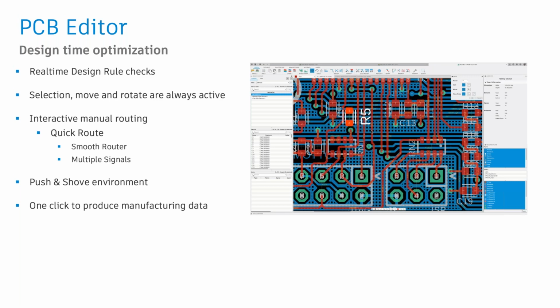Traditionally, users would have to delete any obstacles that are in the way. They would have to rip up, in other words, any work they've done would be a total waste of time. They would have to erase these components, place the new part, and then do the routing again. Now with Fusion 360, they're able to just place the part, things will get out of the way, and they can use the push and shove routing capabilities of Fusion 360. They'll make their way there. I can't tell you how many clicks, thousands of clicks, are being saved with this new process that we have.